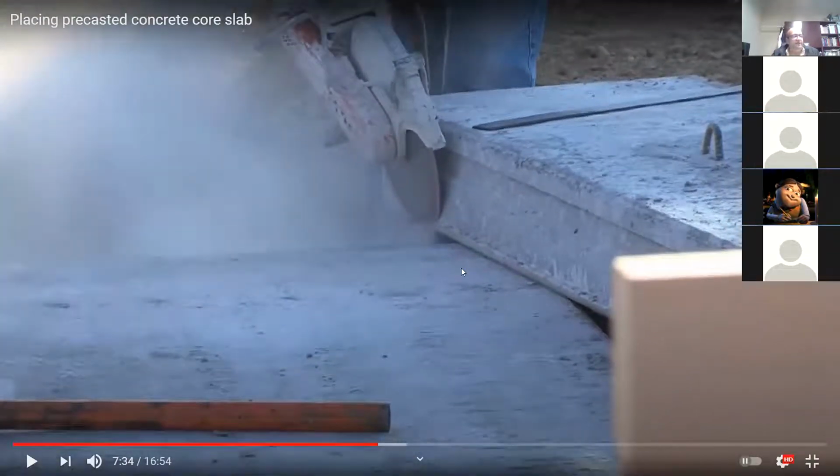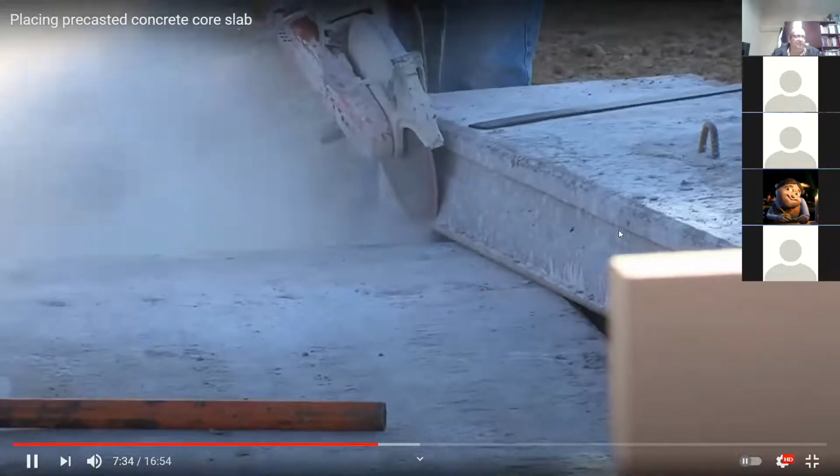So you see what they're doing here? They're able to cut and trim the blank easily, and the whole core, because this is pre-tension. So in pre-tension, there's no problem to trim any part of it. In post-tension, you cannot do this. It's going to be a disaster, and someone can just get killed easily in a case like this in post-tension. So in pre-tension, there's no problem as long as you know what you're doing. Keep this please in mind.